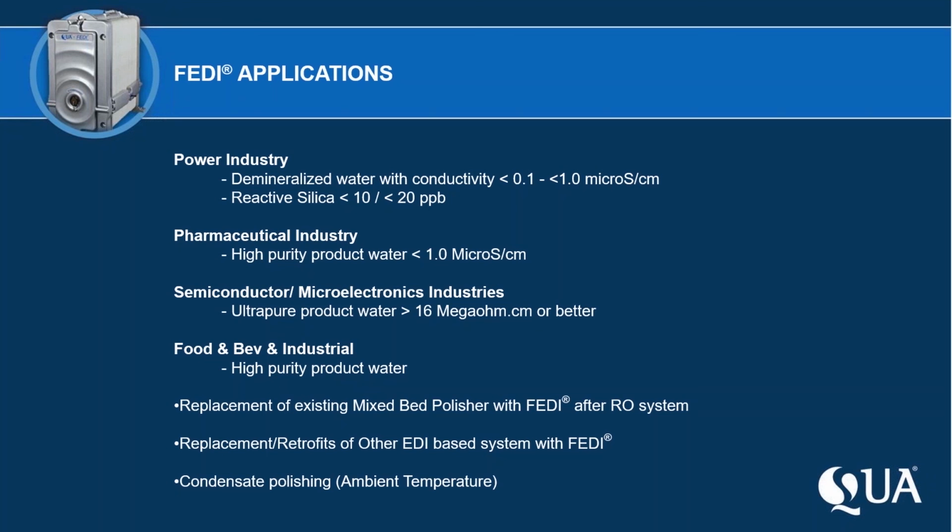But the beauty about EDI or Fedi technology in the pharmaceutical industry is you bring this system into the pharmaceutical site or biopharma site, and you validate it once. So validation and documentation is extremely important in the pharmaceutical industry. One of the things they don't like doing is bringing equipment in and out all the time. It requires shutdown of the pharmaceutical plant, which they can't afford. They have to revalidate for ion exchange resin.